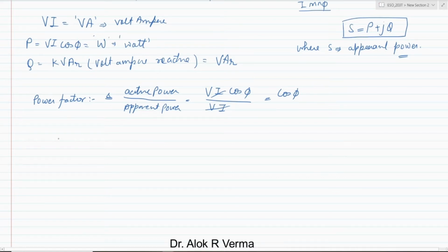So basically, if we remember R, then we have XC, XL, then it was something like XL minus XC, and then we used to have this Z, right? So this net phi, the cos phi will be nothing but R by Z.